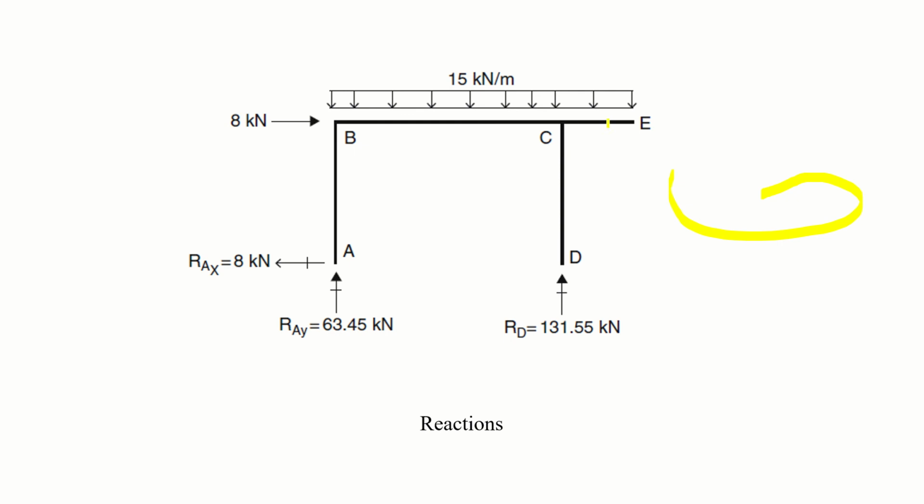CE is the weakest member, and what you have to do is just take its bending moment and apply it here, because nothing can be resisted here. There can be no vertical force here, no horizontal force here, no moment resistance here, because this is a free end, it is just hanging. So just find this bending moment and apply it at joint C. The tricky point will be how you balance the joint C.